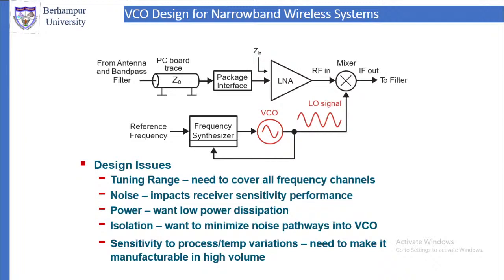Then the noise due to this VCO will impact receiver sensitivity or performance. Higher noise will impact more, so noise should be less. Then power: you require low power dissipation. Power issue is that low power dissipation is required.